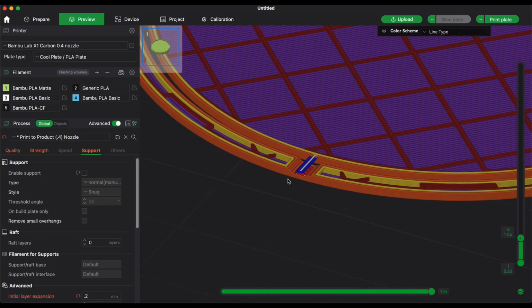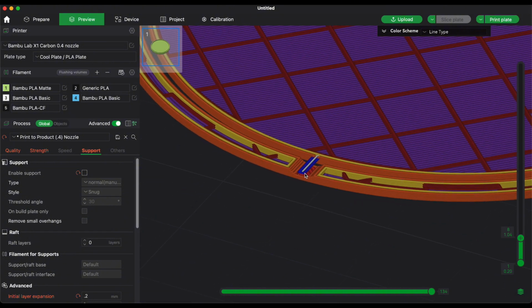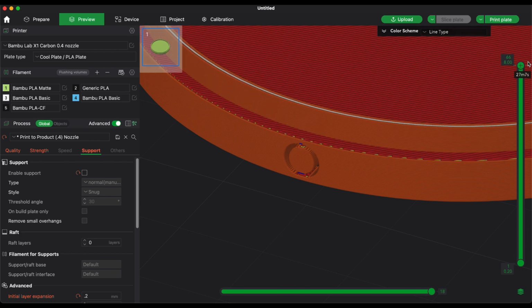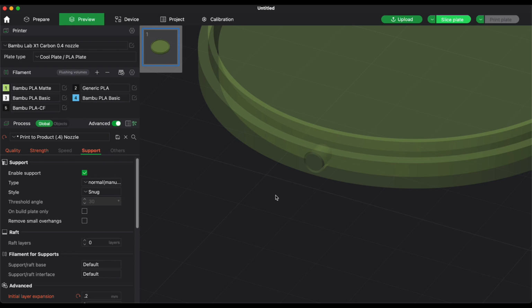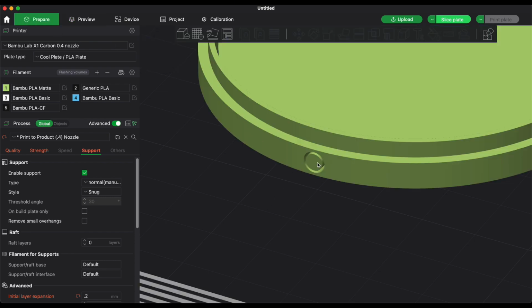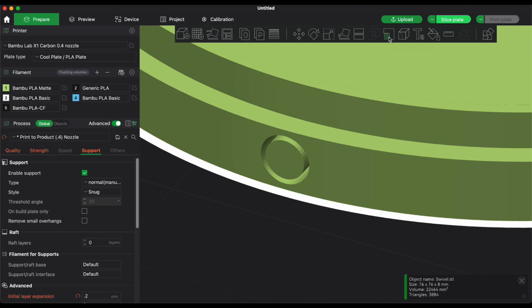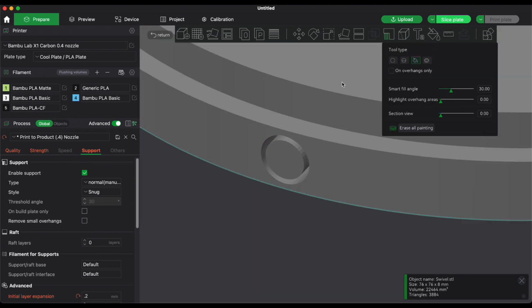Now, while technically you can 3D print this with no issues, and while it would still work, if you want this to be just as flawless or print basically with nearly zero imperfections, well, what you want to do is add some sort of supports here. Now, the reason why you would want to add supports is because it would just basically make this look a little bit cleaner, but otherwise you should have no issues printing this in place. Let's go ahead and click on Create Supports or the Supports painting, then paint around the underside.